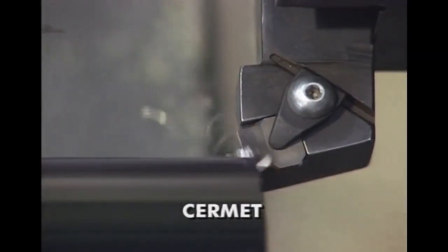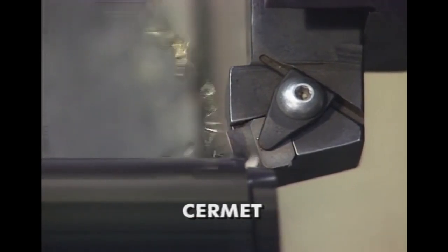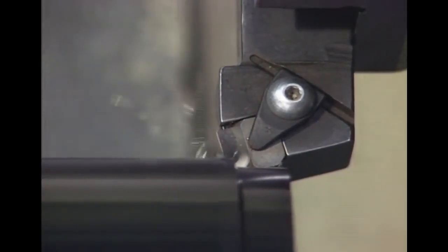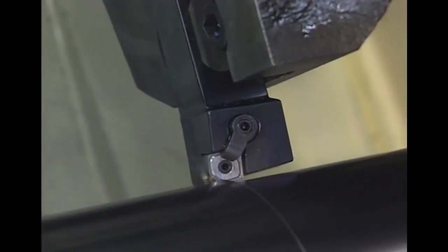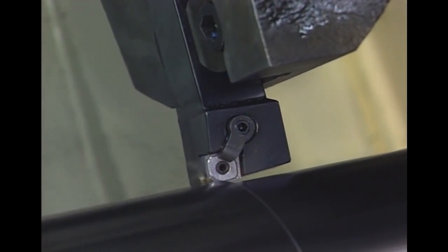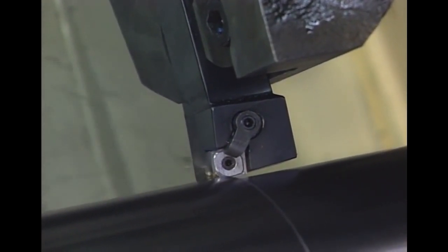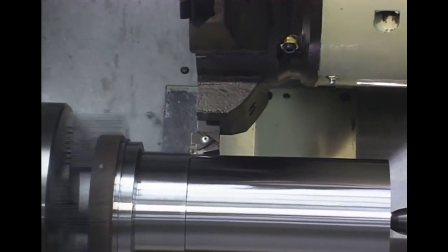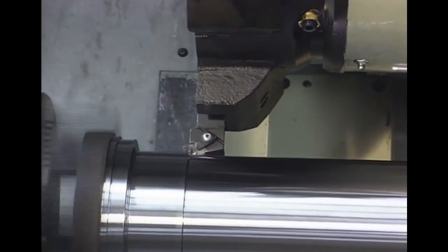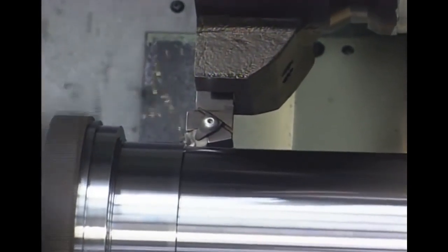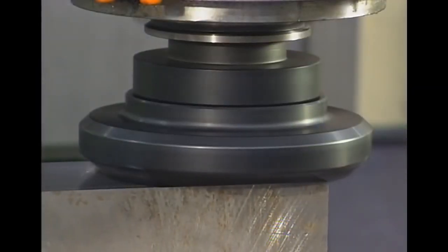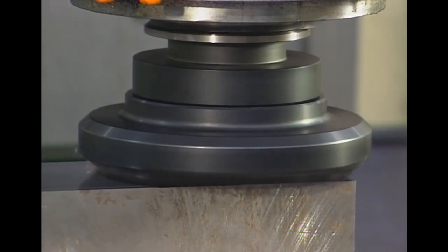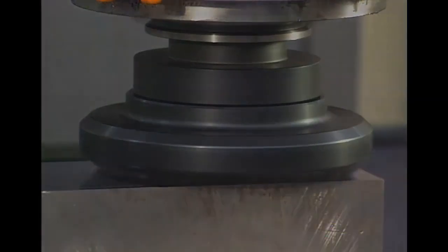Cermet tools are composed of materials commonly applied as coatings to carbide tools, titanium carbide and titanium nitride. The solid cermet insert offers excellent resistance to various causes of wear in machining, especially chemical resistance. Initially used only for semi-finish and finish turning and boring, some cermet grades are now tough enough to handle rough turning as well as milling applications on carbon steels, stainless steels, and some ductile irons.